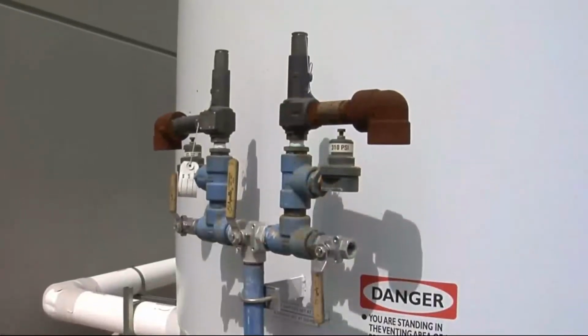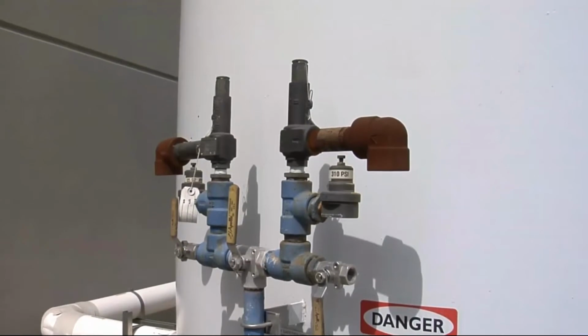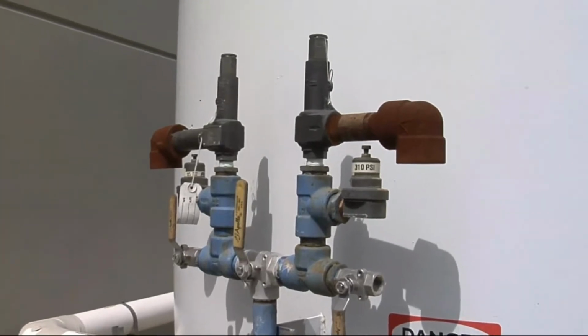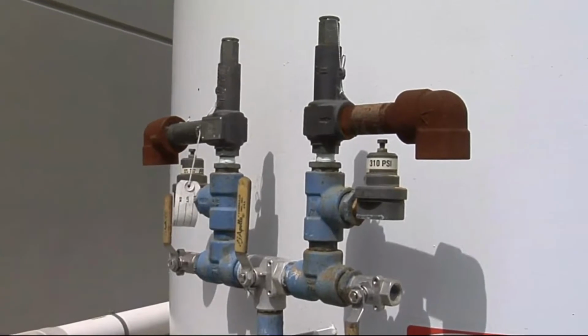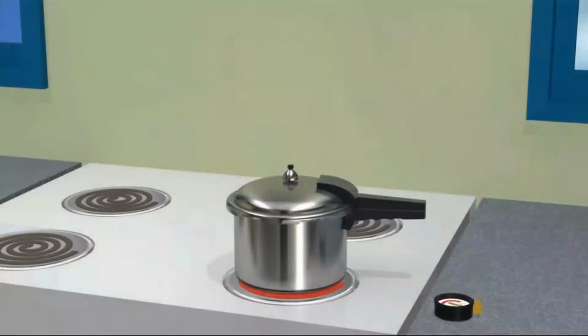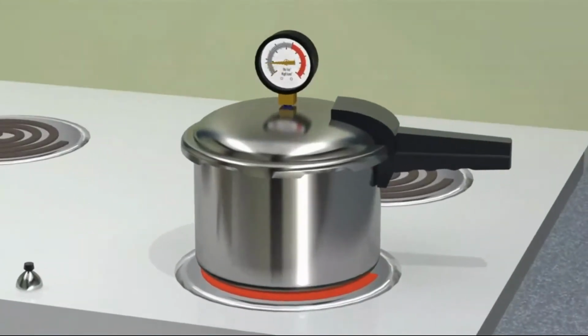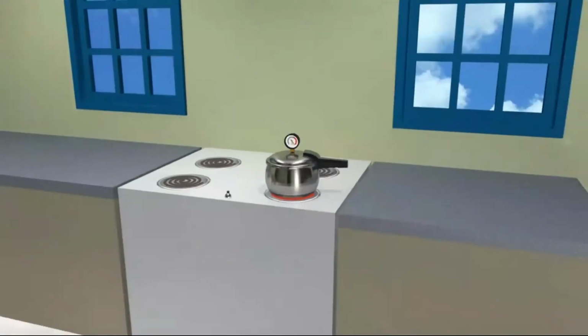It's very important that liquefied hydrogen never be trapped in a container or a section of pipe anywhere in the bulk handling system. Safety relief devices must be installed wherever the pressure can build up to dangerous levels. Here's why. Imagine boiling water in a pot with the lid clamped on. What would happen? Water boils. Steam pressure builds up. And before long, you've got a very hazardous situation.